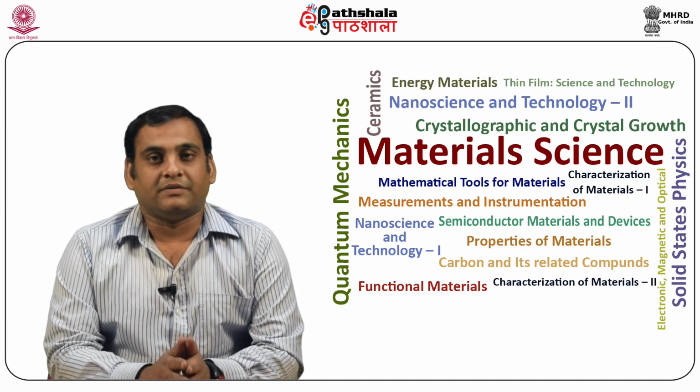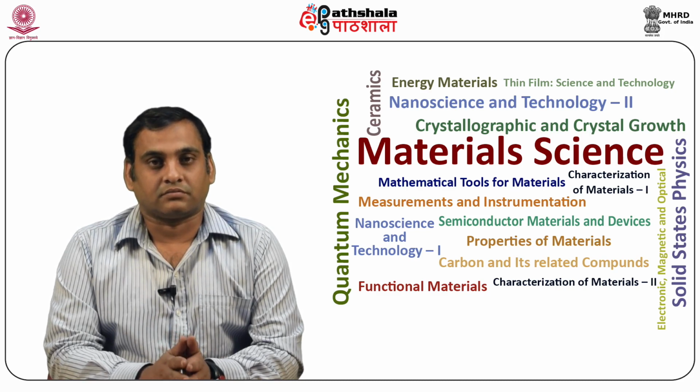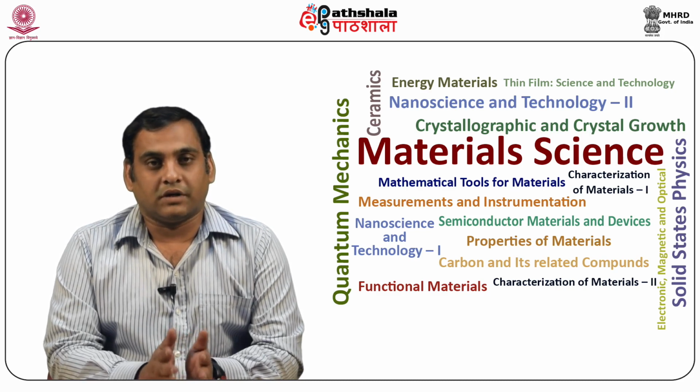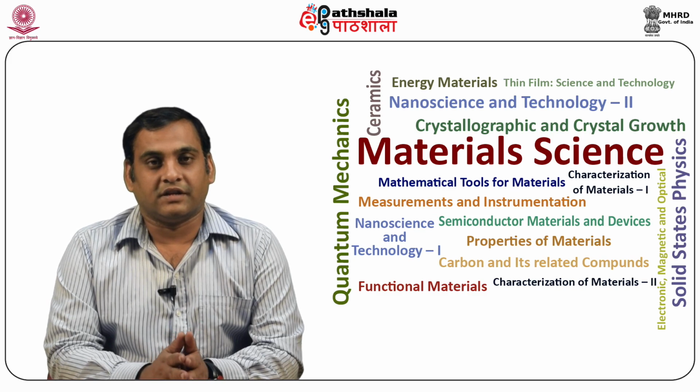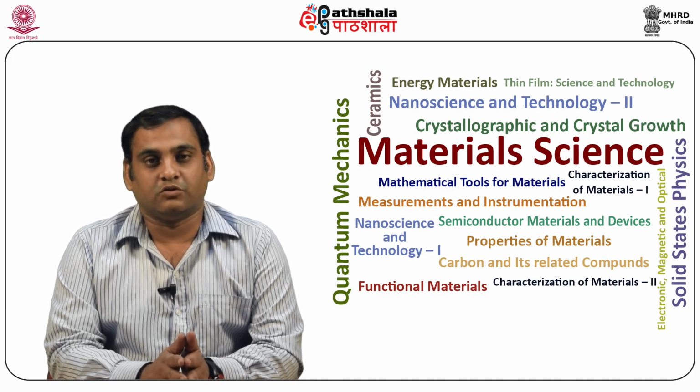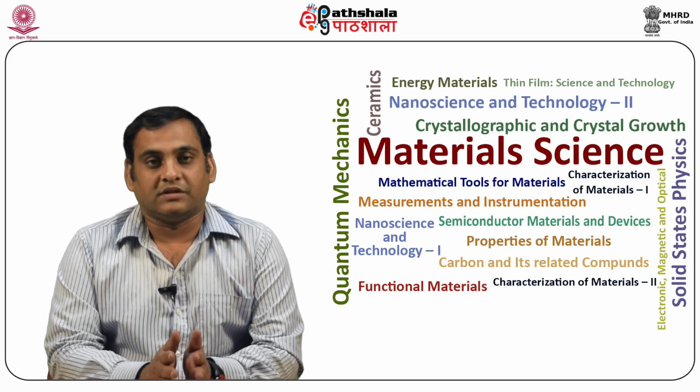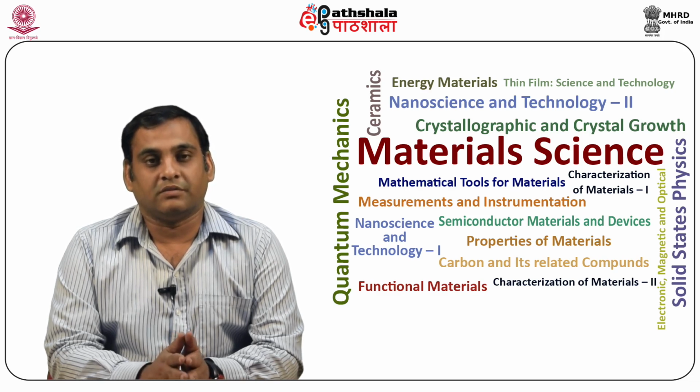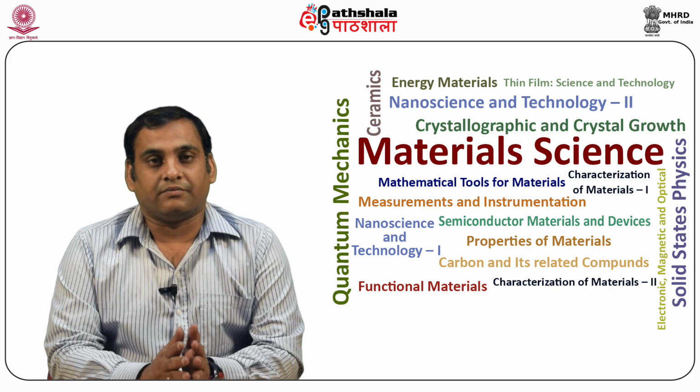The magnetization of a typical ferromagnet is of the order of 1 into 10 to the power 6 ampere per meter, and the demagnetizing fields HD, though smaller, are similar in magnitude. Magnetostatic energies, minus half mu 0 HD dot M, are therefore of the order of 10 to the power 6 joule per meter cube. An atomic volume is typically 0.2 nanometer whole cube, so the corresponding energy per atom is 1 into 10 to the power minus 23 joule, which is equivalent to a temperature of about 1 Kelvin.